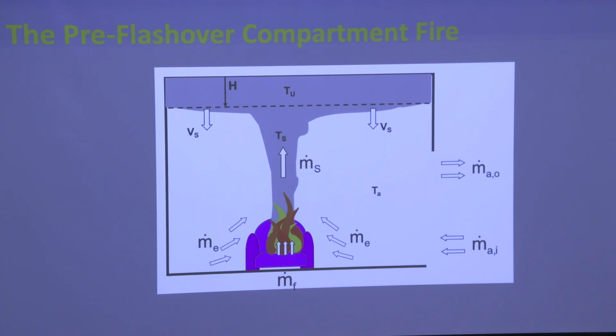So now, why is that useful? Because as the smoke layer descends and its temperature increases, I can create a criteria that defines the condition for flashover. And that criteria, once you attain flashover, because you know what the velocity of descent is of the smoke layer, allows you to calculate the time to flashover, or the TF, okay? So the objective is purely to calculate TF, and therefore, for that purpose, taking this particular approach actually works, okay?